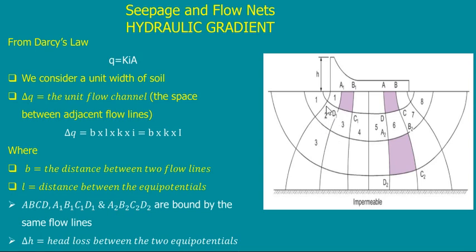Draw a circle here in your mind. Just draw a circle here and draw another circle here, and then draw a line tangent to these circles and perpendicular to the flow lines. Then you get this one, and so on. The next one, next one, next one, till you reach the final shape. So when we finish